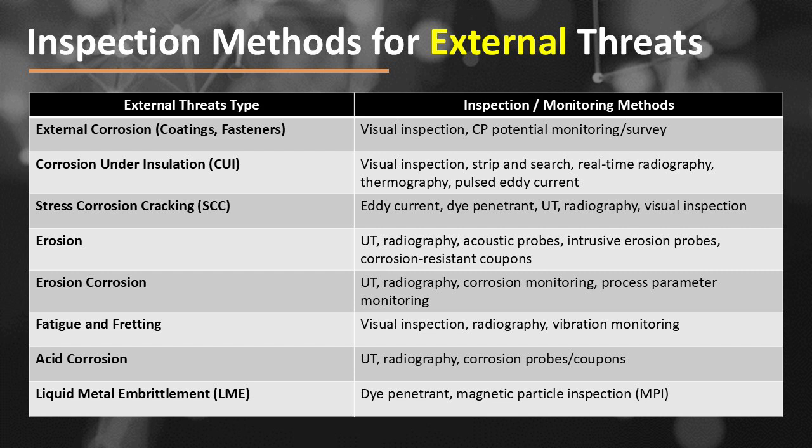If the external threat type is liquid metal embrittlement or LME, then the inspection or monitoring methods that can be used are dye penetrant and magnetic particle inspection or MPI.